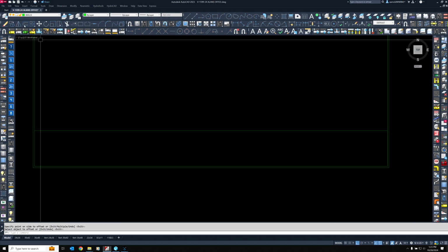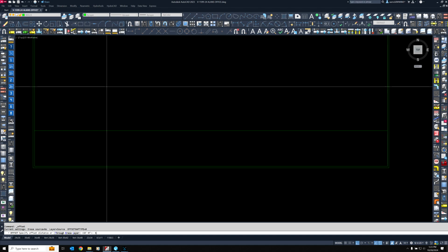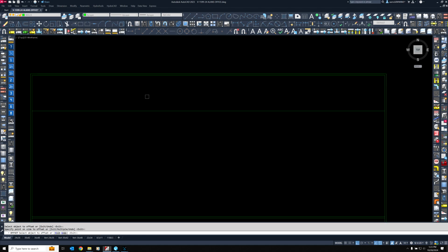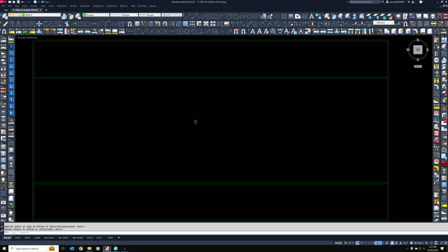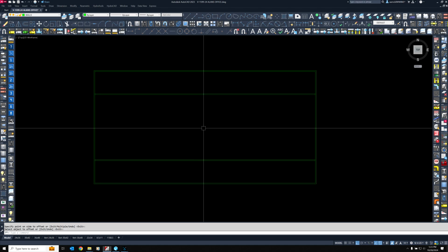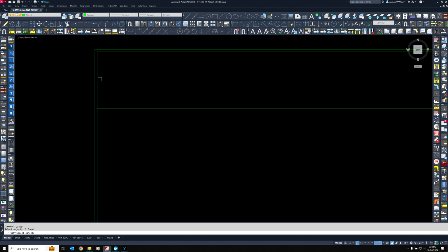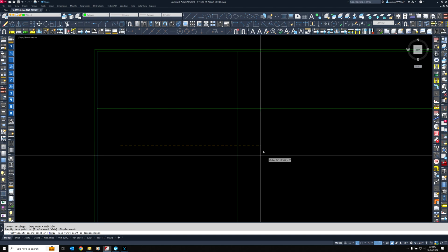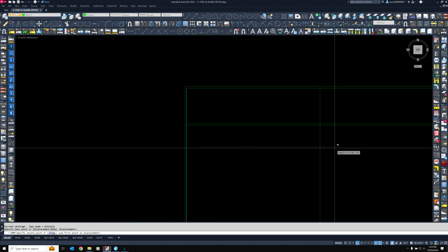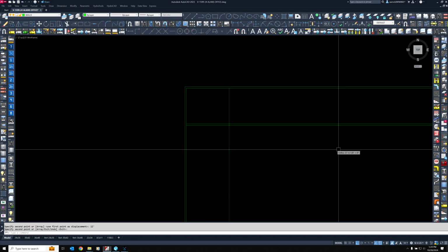And click your object, move it north. Good. All right, now offset 5 inches, and that'll be the outside of the room. Now we've got the start. And our rooms are 12 feet long, so let's copy. Try not to go too fast. Hit the copy command, left click, hit enter, and then pick anywhere in the drawing and left click and start moving. So that first room is 12 feet.